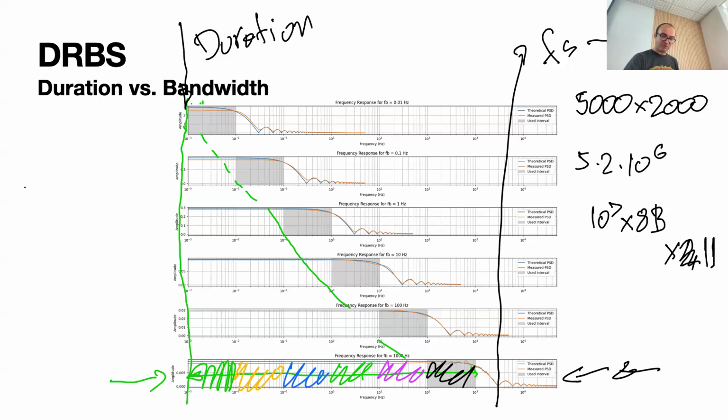That's why I was generating 6 PRBSs. Since we limit the amount of data, it complicates things a little bit. So you have to generate the first one, make an excitation measurement, generate the second one, make an excitation measurement. So you have to repeat this measurement 6 times, but the amount of data is practically nothing. You save tons of space and time just by doing this trick.